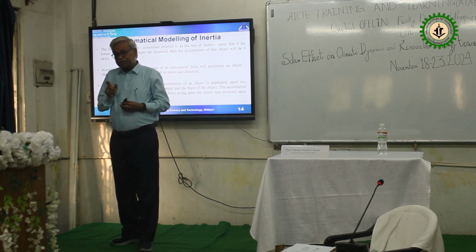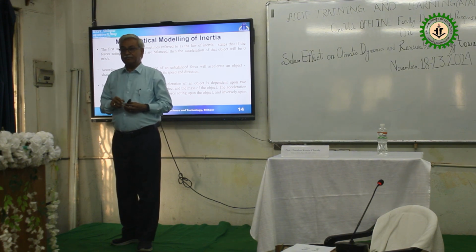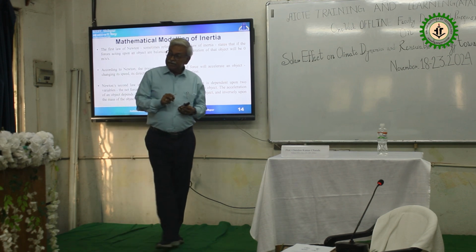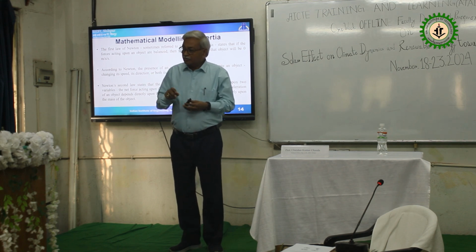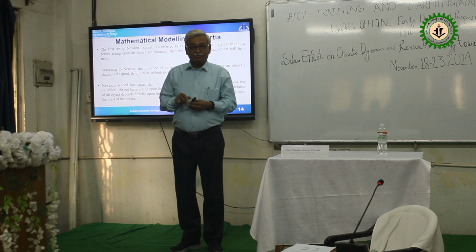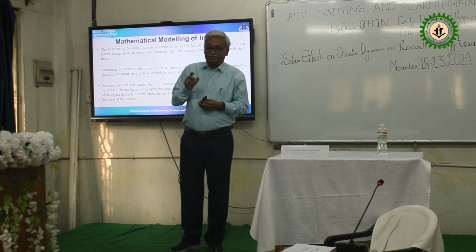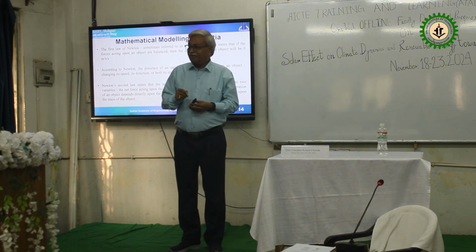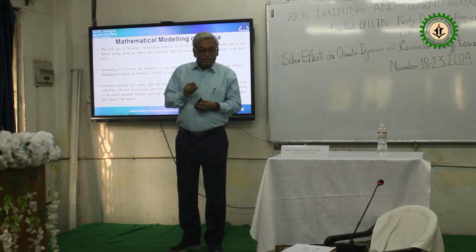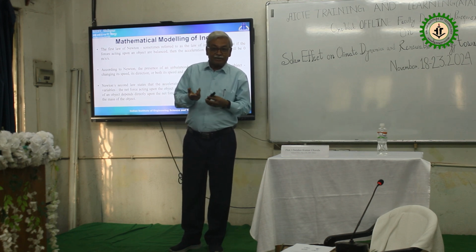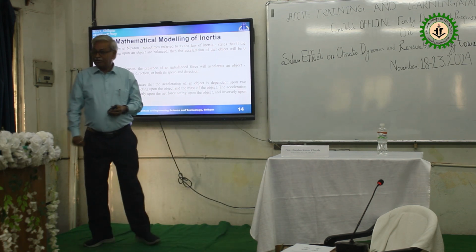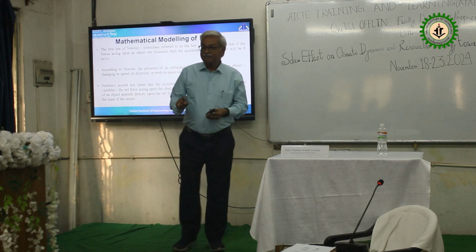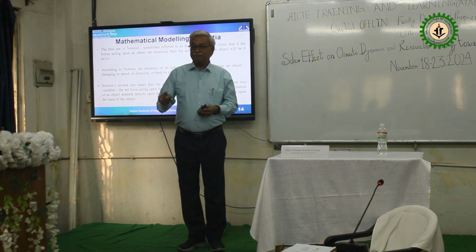As long as the sinusoidal function, imagine the mechanical energy is constant in nature in a synchronous generator, there is no stability issue that will come. But if the mechanical energy is more than the electrical energy requirement or vice versa, then what will happen? The rotor will start swinging. And from there a very important equation has come from the exam point of view. We generally ask the students the swing equation. So, if you want to derive inertia in a time domain and heterogeneous mode, we have to bring in this swing equation. Swing equation, you know what is swing equation? M d squared delta by dt squared is equal to Pm minus Pe.